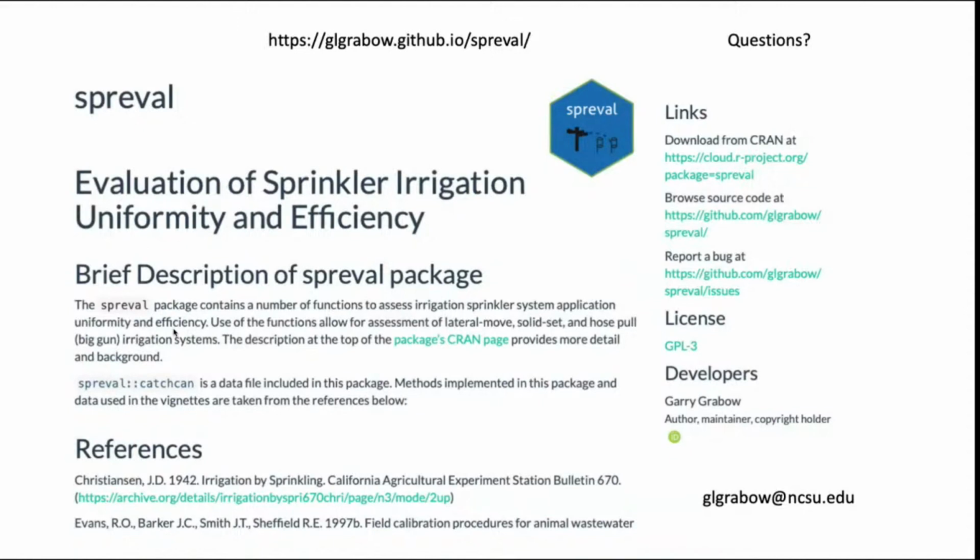But screen filters and disc filters are the two general types, and you have to size those correctly for a certain flow rate so that you don't overextend them. They have enough capacity, and those will be rated in gallons per minute per square foot of screen or disc area. There are different screen sizes, different disc sizes in microns, and screen sizes and mesh sizes. They're all a little different, but there's a variety of screens and filters you can use.